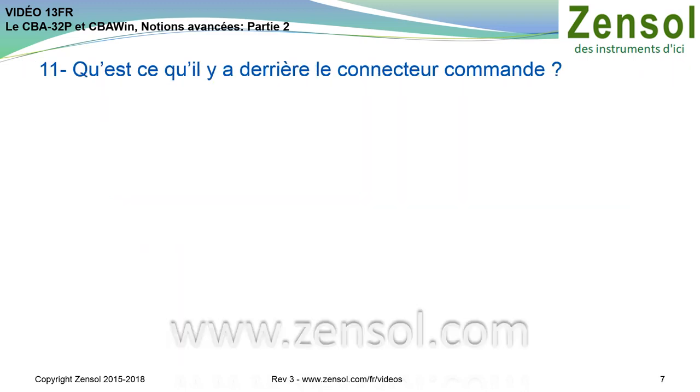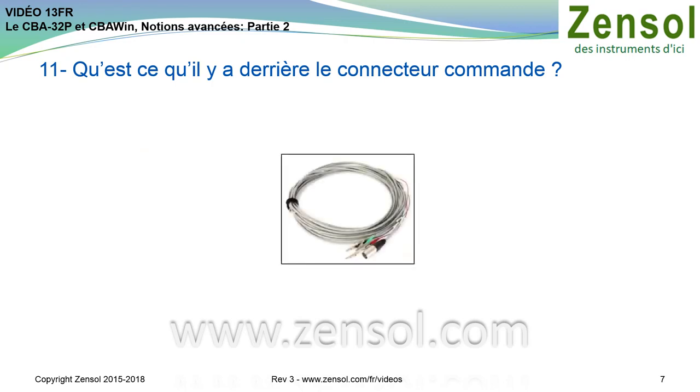What's behind the control connector? Once the control cable has been connected to the circuit breaker cabinet, the CBA-32P takes full control of the circuit breaker's closing and opening operations. The cable is designed in such a way that it completes the control circuit for the closing and opening operation. It is made up of 4 conductors, 2 common, one for the closing coil and the other for the opening coil.